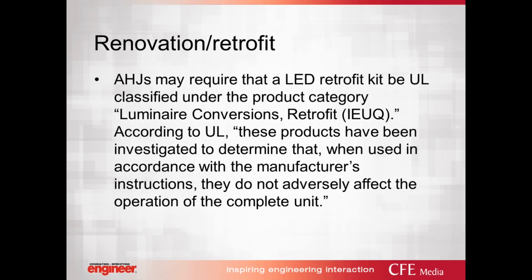So I'll give you an example. Let's say there is a fluorescent fixture manufactured by company ABC, and you've got an XYZ retrofit kit. And the question is, can you put that retrofit kit into the ABC manufactured fixture? So UL actually publishes a listing of these luminaire conversion retrofits that are acceptable. So you'd definitely want to make sure that your XYZ retrofit is UL listed with the ABC manufacturer.